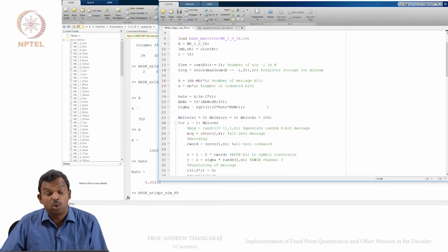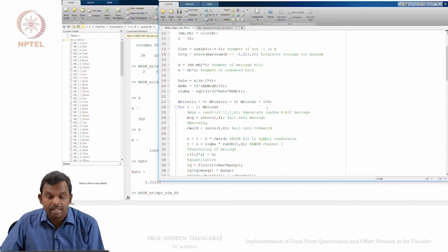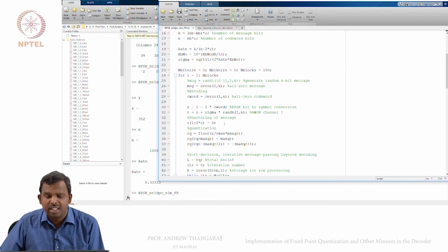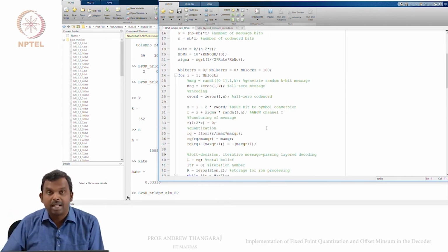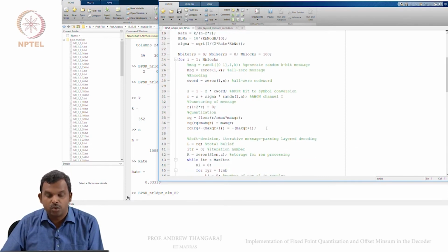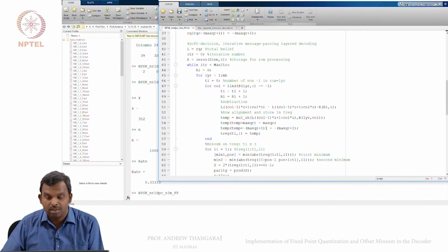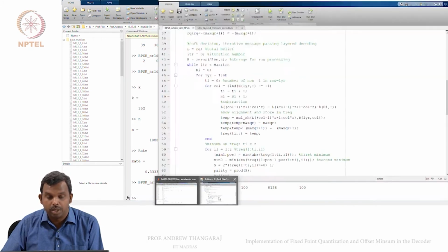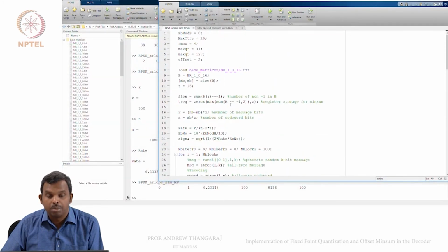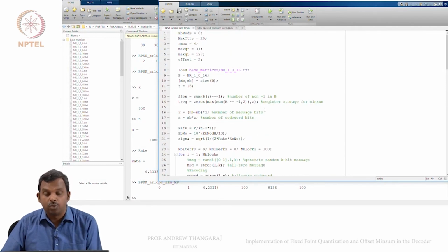We've incorporated most details that need to be there. The puncturing of the first part we did, but we didn't incorporate the shortening and the puncturing of the parity. That I will, like I said, leave as an exercise for you to make a modification. It's not too difficult. The changes have to be done here and there. So here you can see the rate is 1, all the things were in error. So 0 dB Eb/N0 is too low, 2 dB is pretty good, and 3 I'm sure will be even better for these kind of code rates.